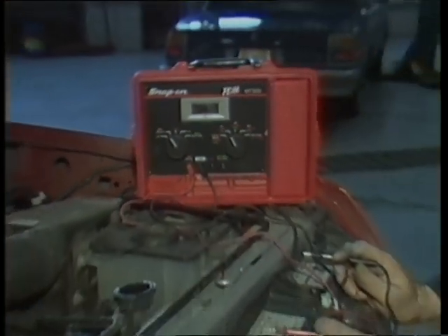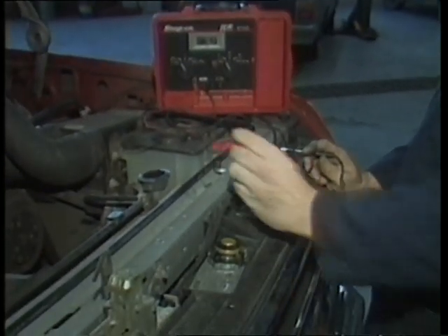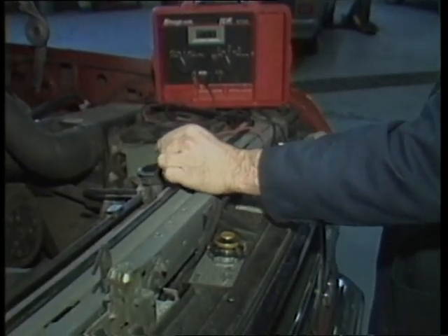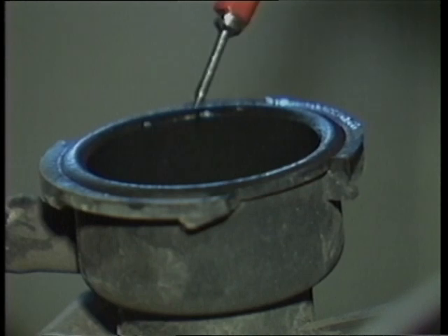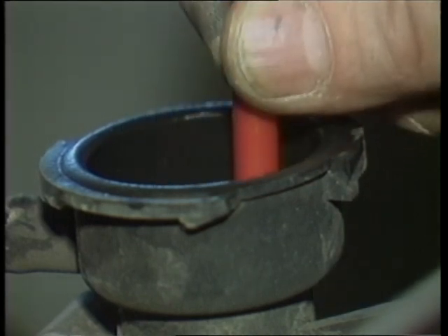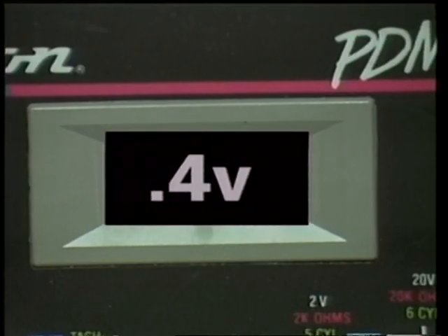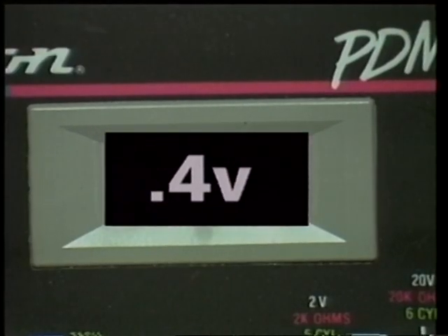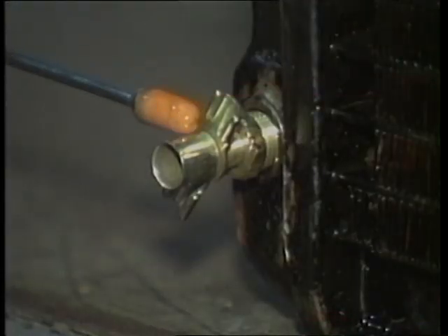A handy trick for checking the age and condition of the antifreeze solution is to use a voltmeter. Stick one probe into the coolant and ground the other probe. Then read your meter. If your voltmeter reads over 0.4 volts, it is time to replace the coolant. A high voltage reading shows that the coolant is very acidic and will corrode internal components.